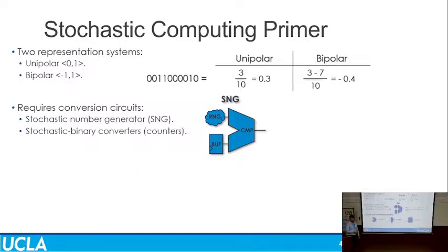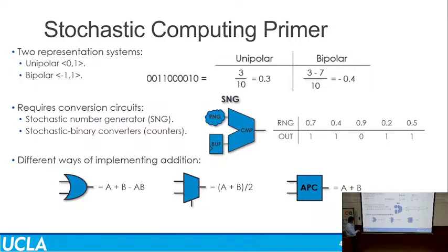Sorry, basic question. It assumes that all our computations are for numbers between 0 and 1, right? How do you... Yeah, so that is just you scale the numbers first. So once you get a number, let's say an integer, you first scale the numbers, and then everything is a fraction between 0 and 1. Right. So this is essentially a saturating adder, and this is what we use because this works out much, much better because you don't get into other numerical issues.